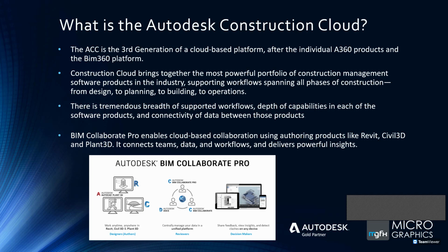That is a particular software that enables, and we'll talk about that a little later as well, the collaboration of CAD software like Revit, Civil 3D and Plant, whereby in Revit's terms you work with worksets, and you author the 3D model concurrently, and obviously share that with the non-Revit users particularly.